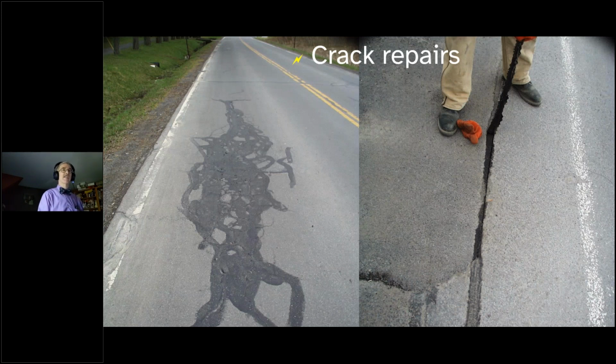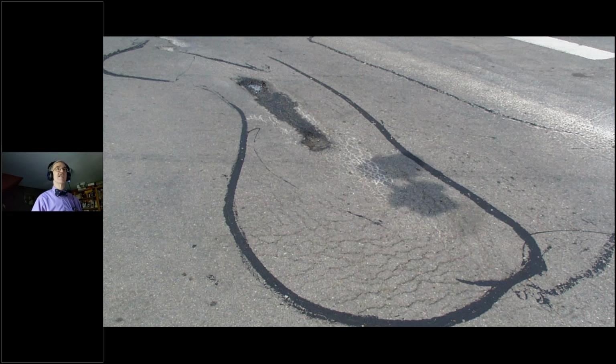What happened obviously on the right is they didn't clean it properly and it didn't stick. You've got to clean the crack out. A heat lance or an air compressor that's got a proper oil water separator is a minimum. Get it dry, get it clean, and don't do it when it's going to rain. But good candidate selection is the biggest issue with cracks. Okay, this isn't a good candidate. This is even worse.